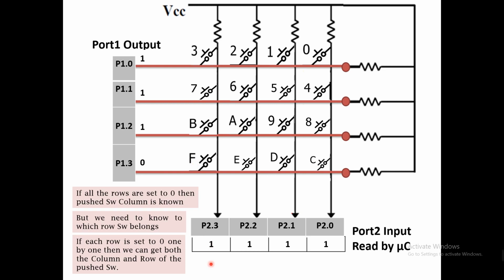It looks like it's a slow and time-taking process, but it is not, because microcontroller commands work in microseconds, maybe nanoseconds in new microcontrollers, but okay, microseconds. And if someone pushes the switch, it stays at least 5 milliseconds. The shortest state could be 5 or 10 milliseconds. So this switch will remain closed for a much longer time than the scanning time.